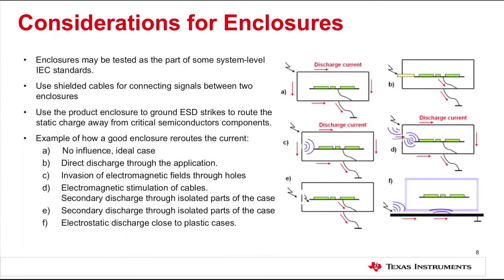As a general guideline, if possible, use shielded cables for connections between 2 enclosures. Some suggestions for routing static charges away from the active circuitry are illustrated on the diagrams on the screen. Please take a moment to review them.